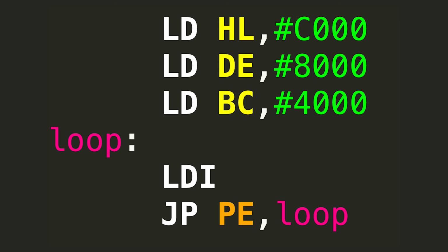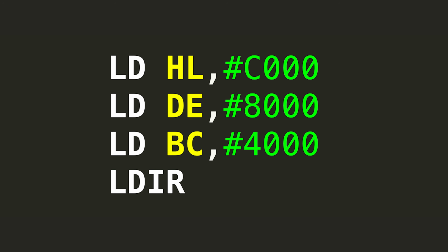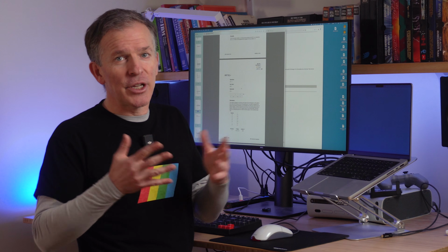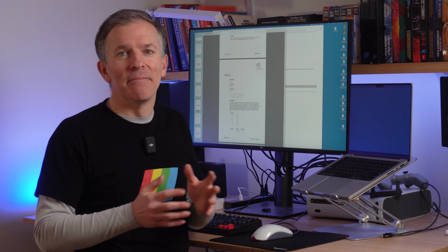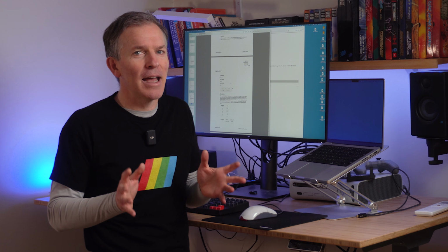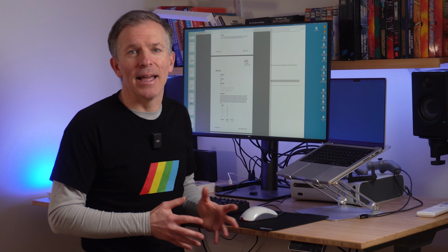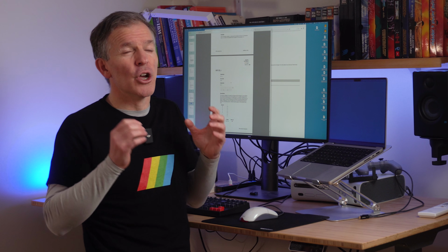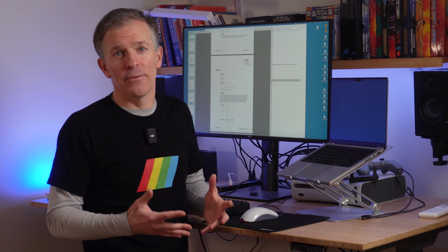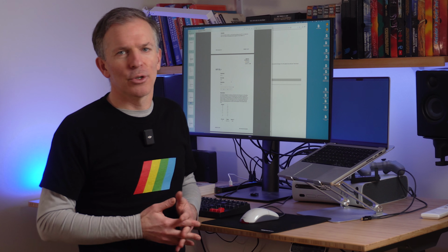And as if that wasn't enough, the Z80 designers decided to take it one step beyond and implement LDIR, which actually implements the loop itself and continues copying until BC is at 0. I imagine for anyone who didn't grow up with Z80 assembly, this monster of an instruction is just a real eyesore. And I totally see that. And at the same time, I remember how LDI is so much more efficient than trying to do the same thing by hand. And since moving data around memory is just so slow and so important for drawing things on the screen, it does have a reserved spot in my heart. But yes, it's still really ugly.